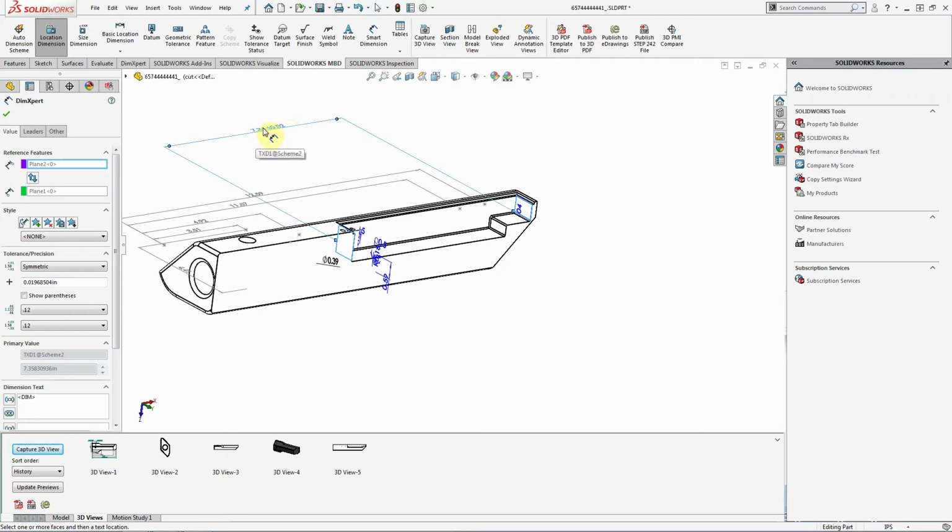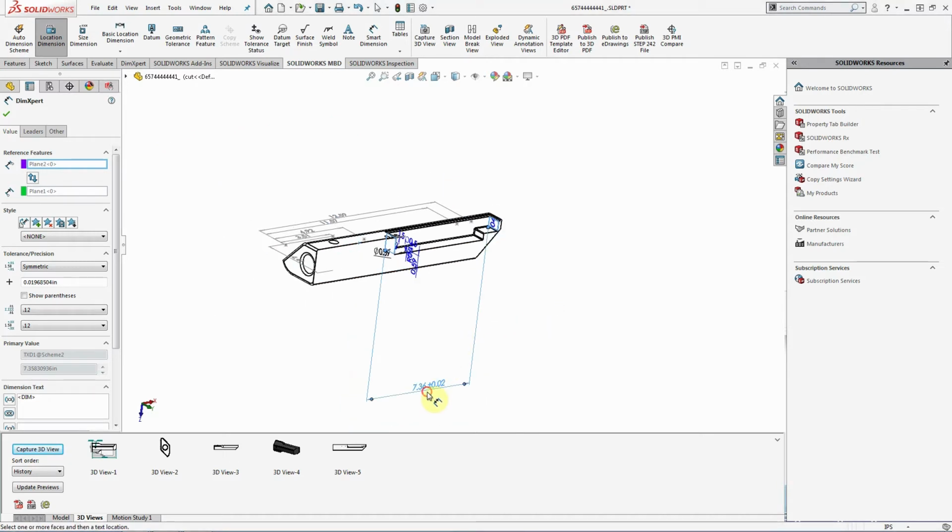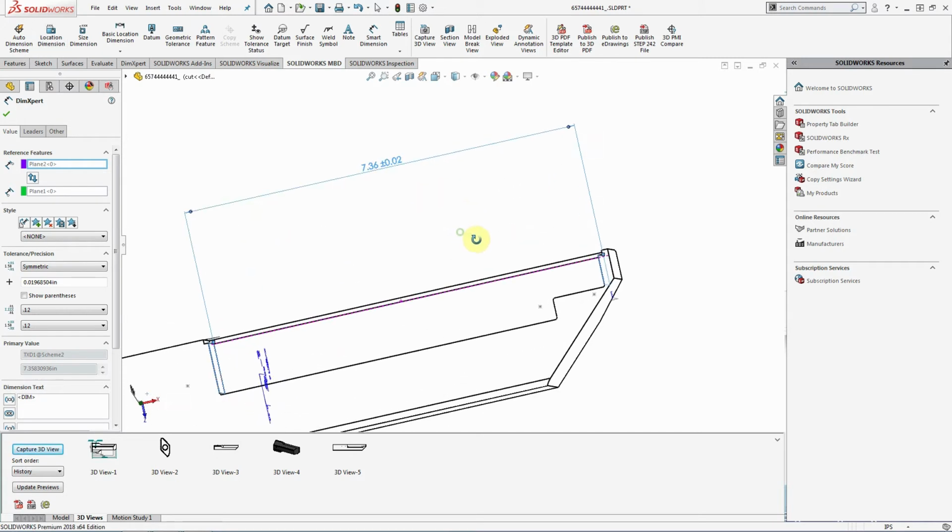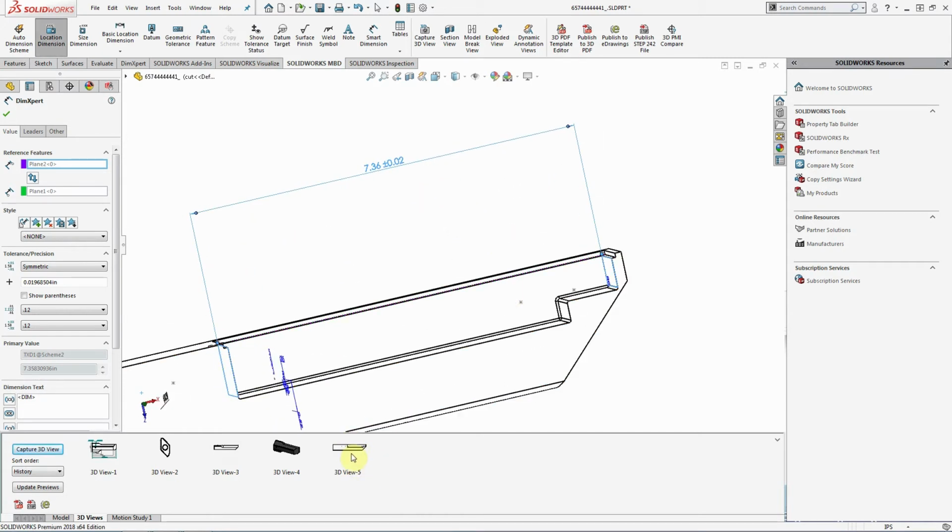So once I place it, just right click, you'll see it placed it on the annotation view front, click on that, and I say set to top. And now I get that annotation in my top annotation view, so I can display it in my top 3D view here.